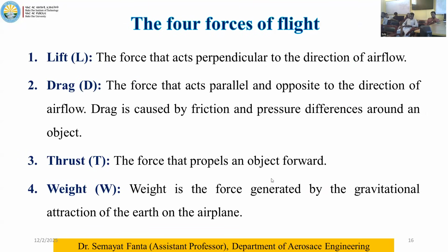Okay, once I say this, it is better to review our four fundamental forces of flight. One is the lift force, the force that acts perpendicular to the direction of airflow. The drag force is the force that acts parallel and opposite to the direction of flow, which is caused by friction and pressure difference. It is a resistance force to the forward motion.